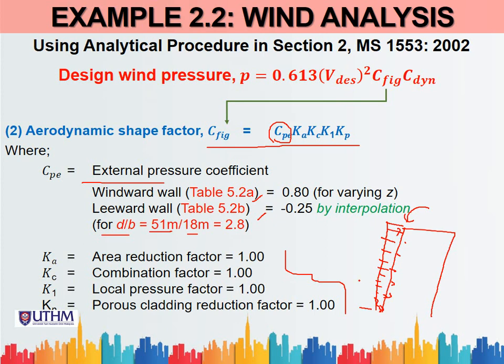Windward side. So here we have H, so the definition for H and Z is the same. But at the leeward side we take it as H. At the windward side we call it Z. We symbolize it as Z because Z is different, it starts from 4 meters, then increases to 7.5, increases again with the additional 3.5, increases again with the additional 3.5 up to 25 meters.